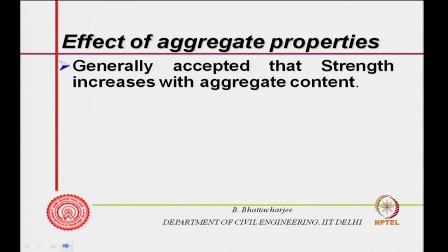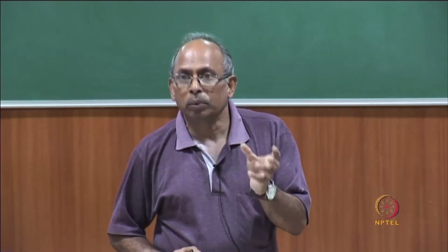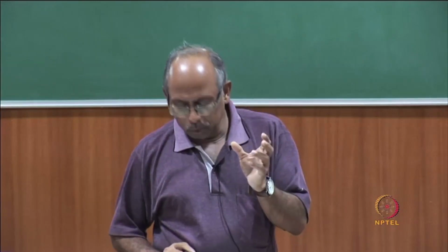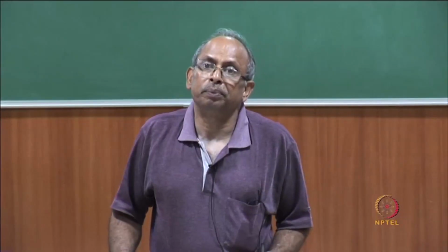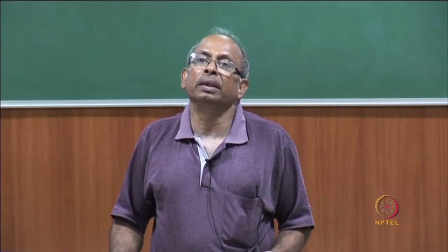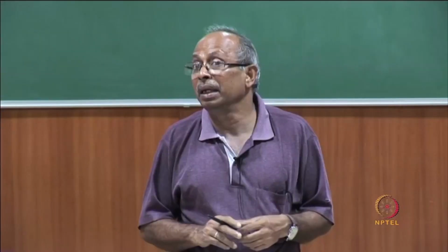It is generally accepted that strength increases with aggregate content in normal concrete, because aggregates themselves are strong, quite often stronger than the paste itself. With increased aggregate content, capillary porosity may decrease. Also, the average stress in the zone of stress concentration reduces. So that is the idea. Everything is stressed in a similar manner, and that is why, as you increase the aggregate, strength increases in ordinary